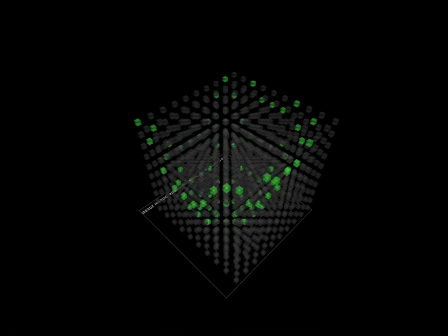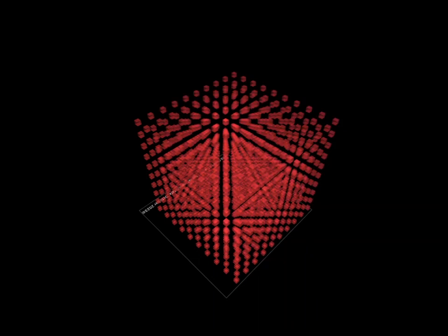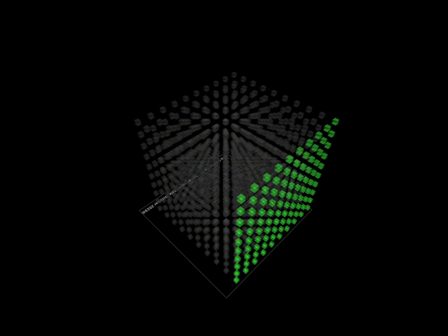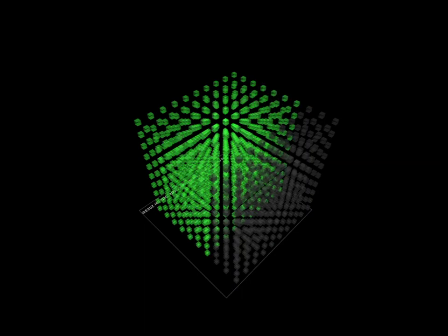To make a latch array that can remember the on/off state of 64 LEDs, we need 8 of these latches. The inputs D0-7 of all the latches are connected together in an 8-bit bus. To load the on/off states of all the 64 LEDs, we simply do this: load the data of the first latch onto the bus. Pull the CP pin of the first latch low then high. Load the data of the second latch onto the bus. Pull the CP pin of the second latch low then high. Load the data of the third latch onto the bus. Pull the CP pin of the third latch low then high. Rinse and repeat.